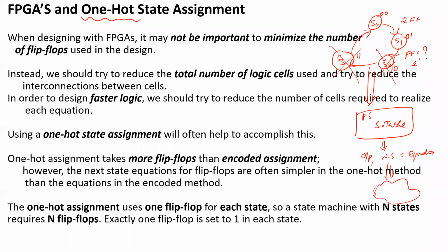So the people are trying to reduce the number of flip-flops, or reduce the number of states, so that the number of flip-flops will be reduced. That is the main focus in the encoded state assignment technique.